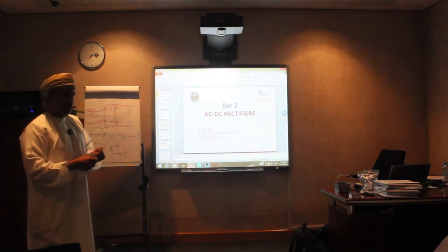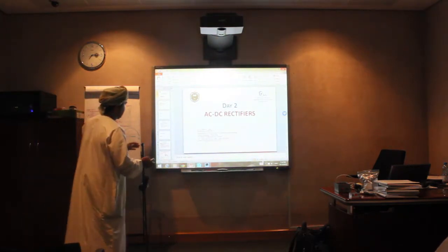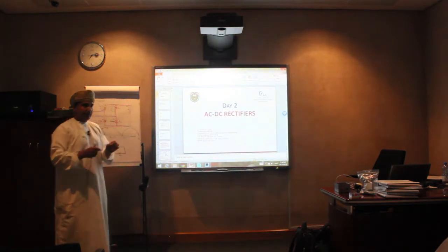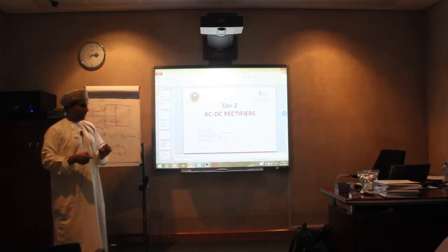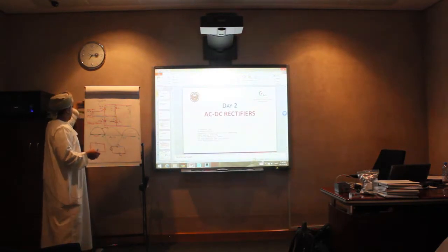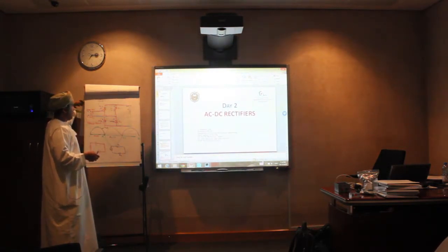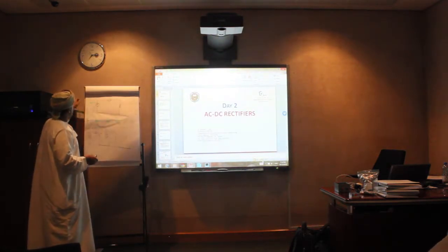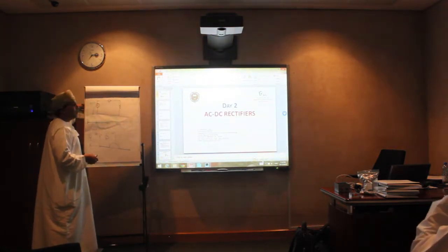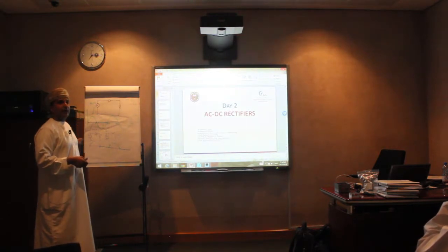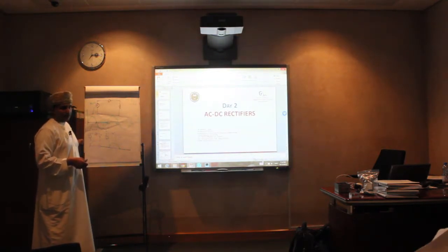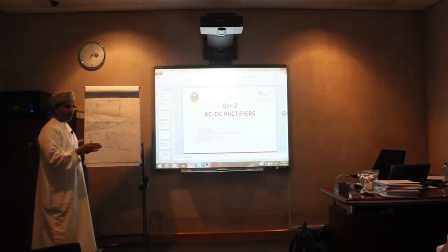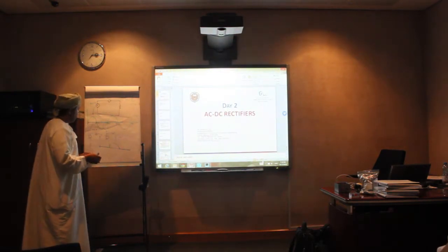The thyristor operates approximately like a diode, but it has slightly different characteristics. We can discuss it later, but it works the same when it is forward biased, and the only difference is that you need to send a current signal to turn it on. Without this condition, you cannot turn it on. So that means it has control.